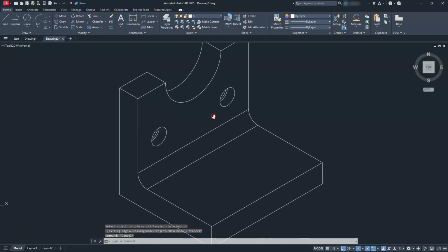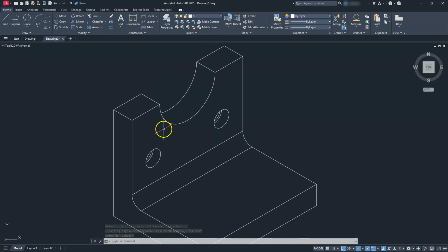All right. And we're almost done here with the top portion, right? All right, so what I'm going to do next is start making my chamfer that's going to be located here along the top. So I'll go to the copy command, and once again, make sure that you're in isometric right. So I'm going to select these two lines. And of course, I'm going to have some extra stuff, but I'm just going to do them that way so I can knock them out really quick.